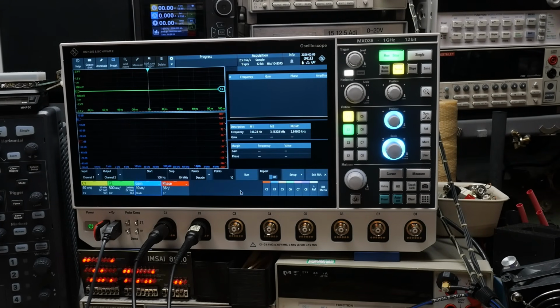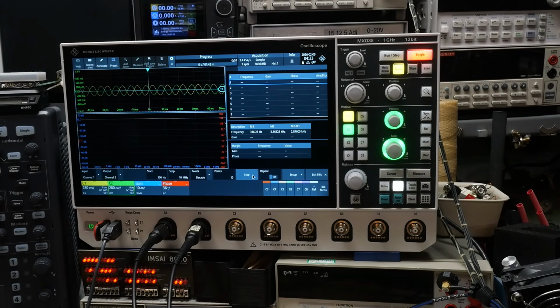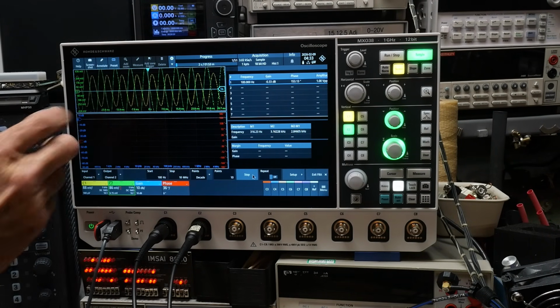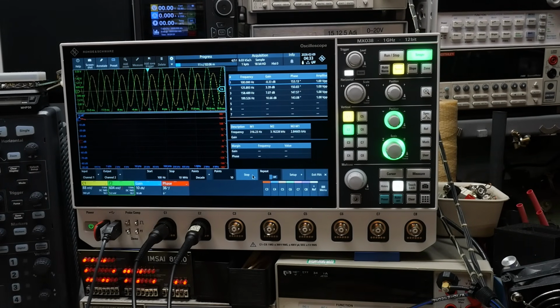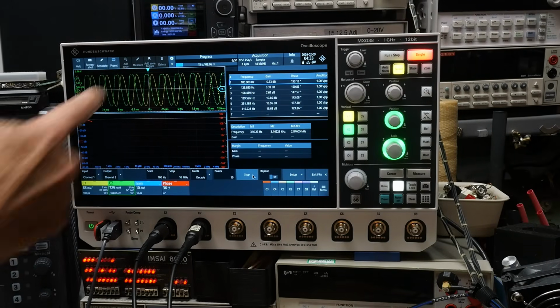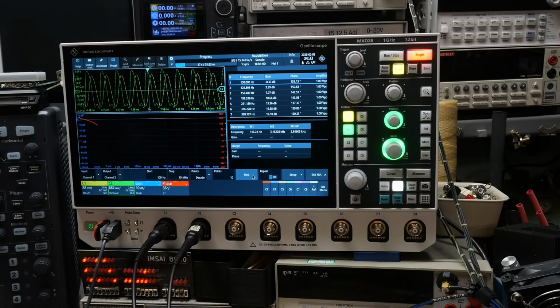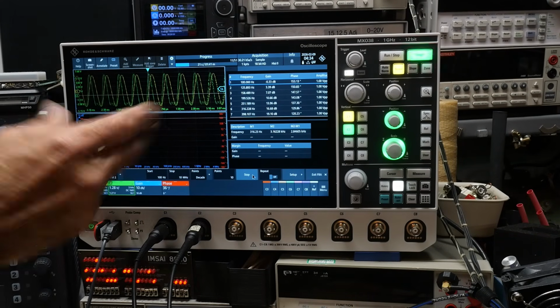10 megahertz. All right, so let's go ahead and run this one. So hopefully you can see this again. Right now, they're going to be about 180 degrees out of phase because it's an inverting amplifier. And then we're going to step along in frequencies. I think now that you've seen the other demonstration, you can see that this one's going to be shifting a little bit in its phase relationship between the two.